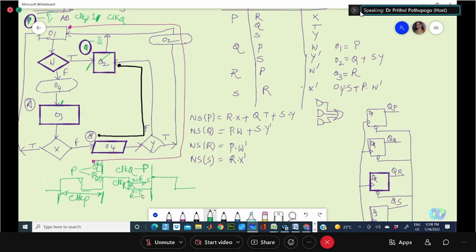That means here, for one clock, the operations that will be performed are: generation of the unconditional outputs, completing the iterations that are instructed, testing any test variables if they are there in the path, and generating the conditional outputs if they are there. That means all the functions that are mentioned in the loop or between two stable states will be completed. Is this clear?